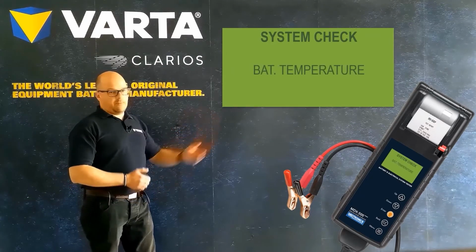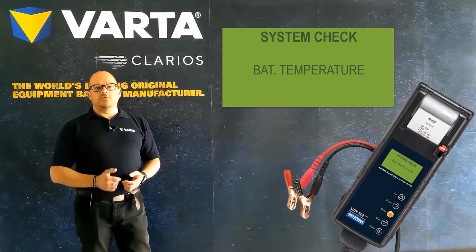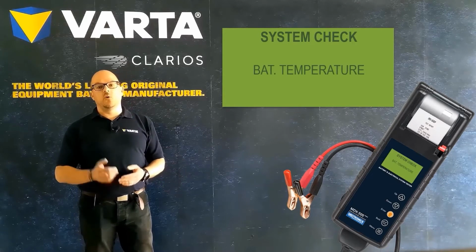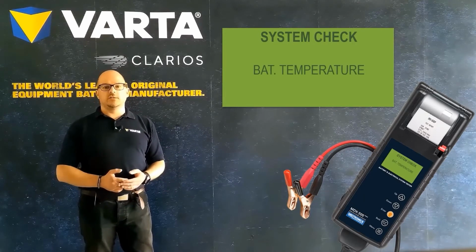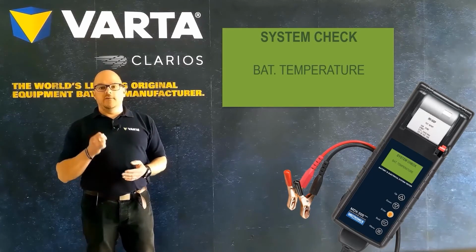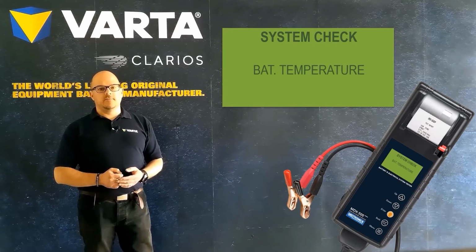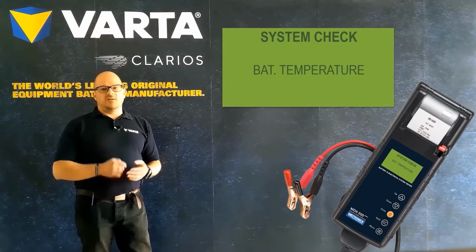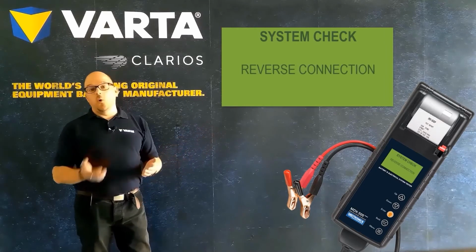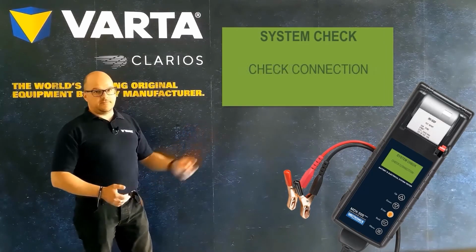Next, battery temperature. The battery temperature is very important, as hotter or colder conditions can cause an increase or decrease to the internal resistance of the battery, and it can give an inaccurate reading if it is not known by the tester. The other likely messages are pretty self-explanatory. So for example, reverse connection or check connection.